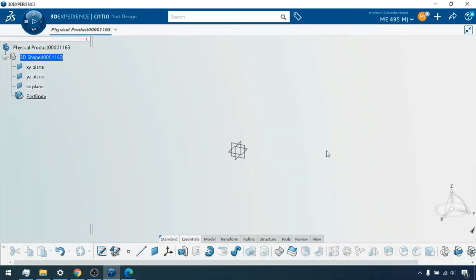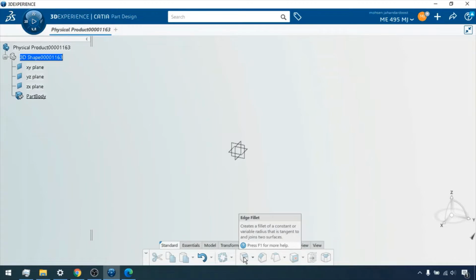In this video, I will talk about the fillet, chamfer, and draft. These are usually the secondary commands. These are not the main commands that you use to create your object, and you can find them in the refine section. So we have a fillet that is part of the design feature. Usually when you design a part and there are sharp edges, you want to use the fillet to smooth the intersection between the two parts or two elements to reduce the stress location.